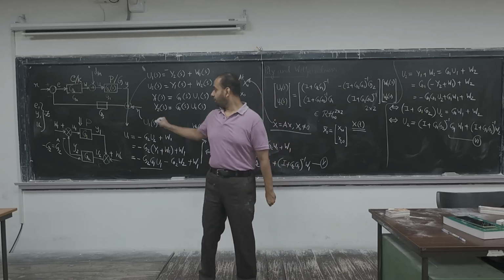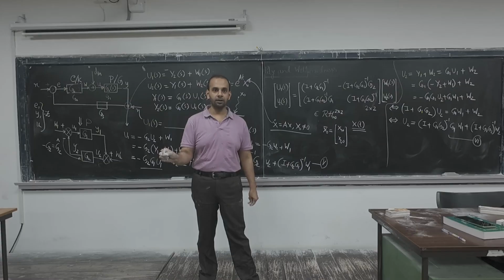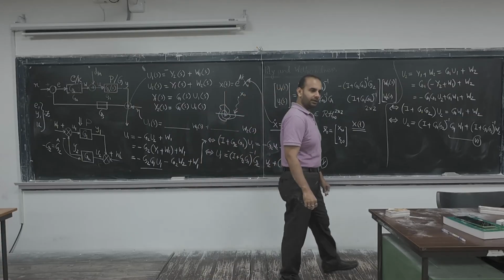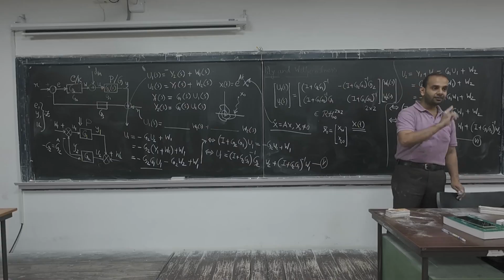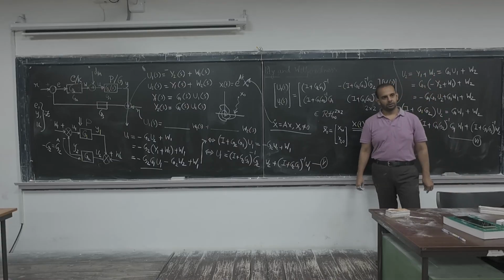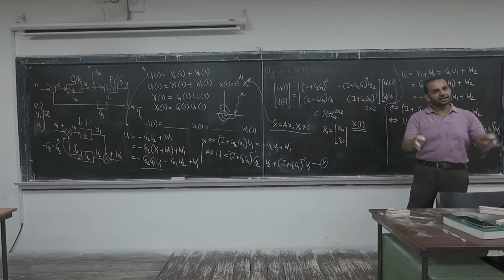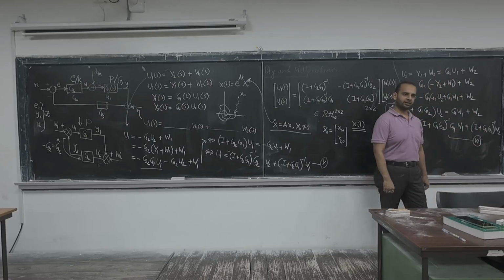Then as a whole, if you excite the system subjected to non-zero initial condition, whether the whole interconnection goes to the origin or not. That is as if the asymptotic stability of the whole interconnection. That is called internal stability. Once again, if you extend the concept of asymptotic stability to an interconnection, not to only one single system, then that is nothing but internal stability.